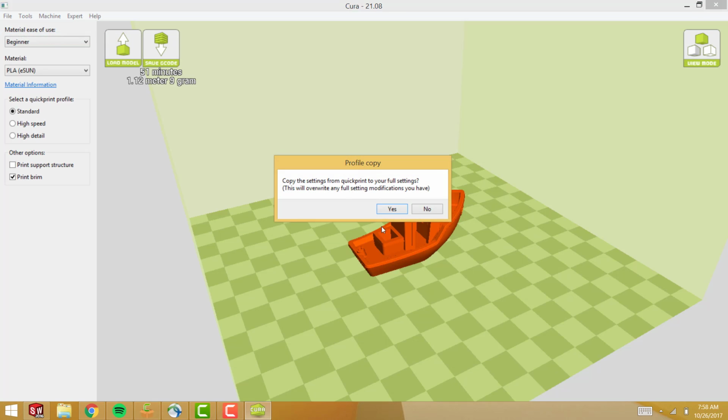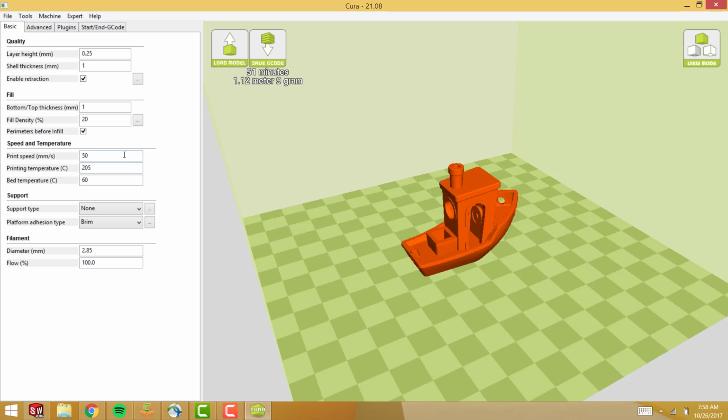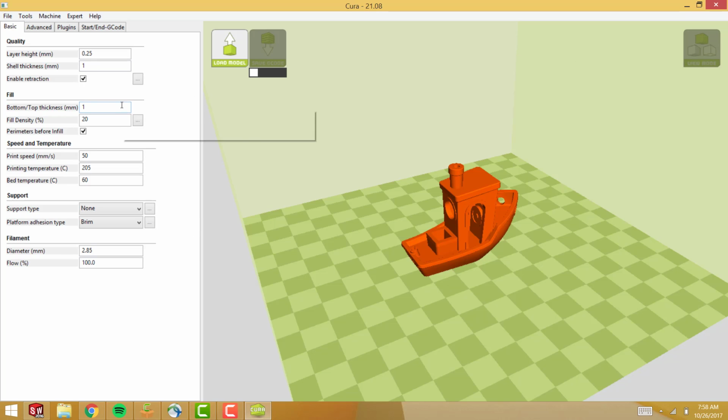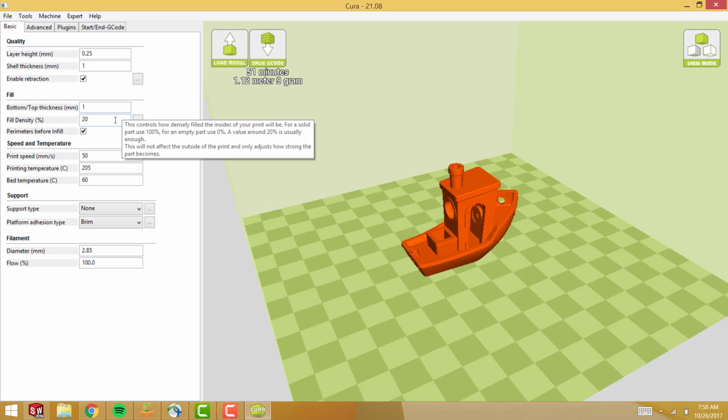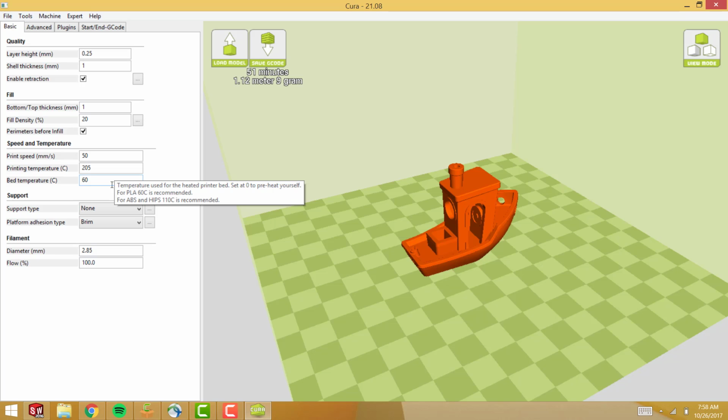You can save the file in 3D print if you're just starting out, or switch to full settings, which gives you more control over your part. I've shown the 5 most important settings in Cura's expert mode. They should already be correct in Cura, but you can always check on the Clemson Makerspace's Canvas site. Make sure to correctly identify the filament diameter because this is subject to change depending on manufacturers, but should be labeled on the spool.